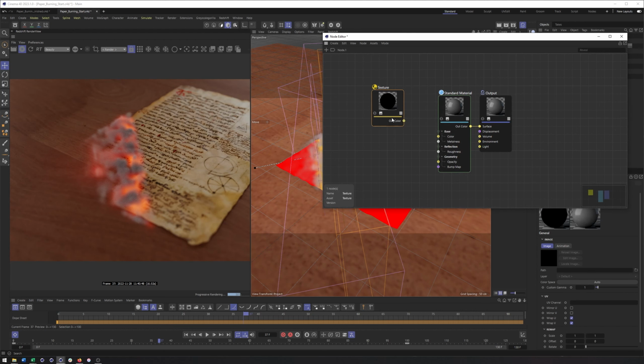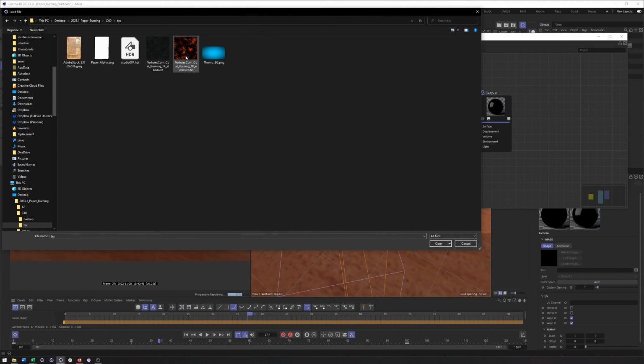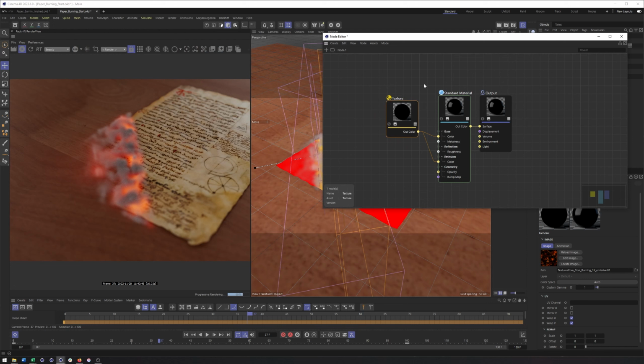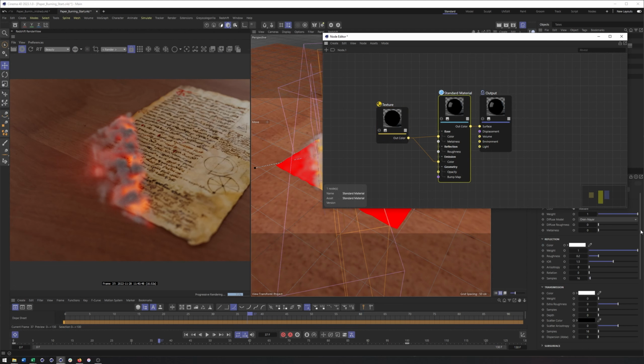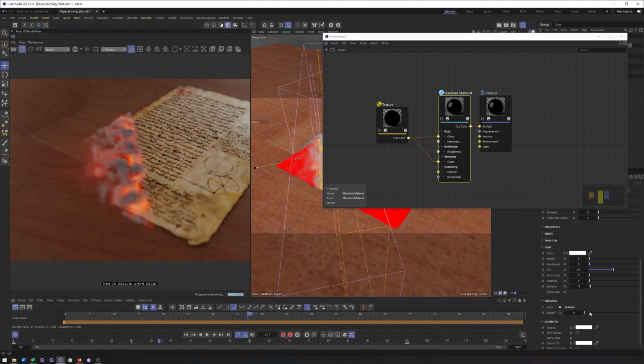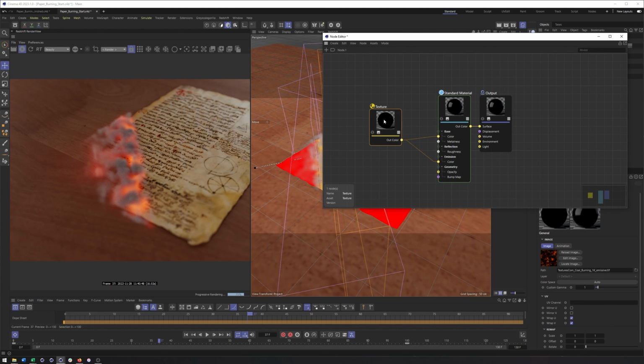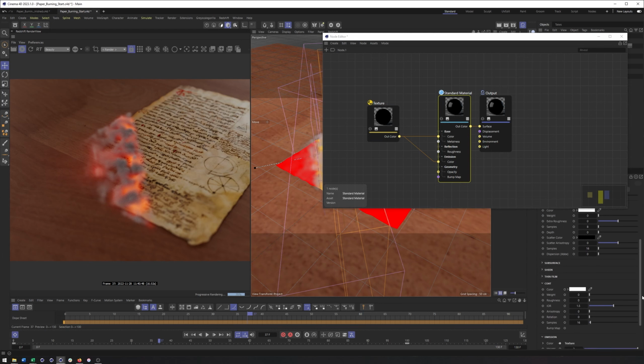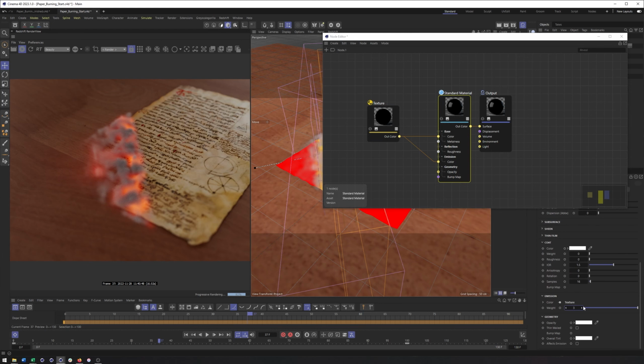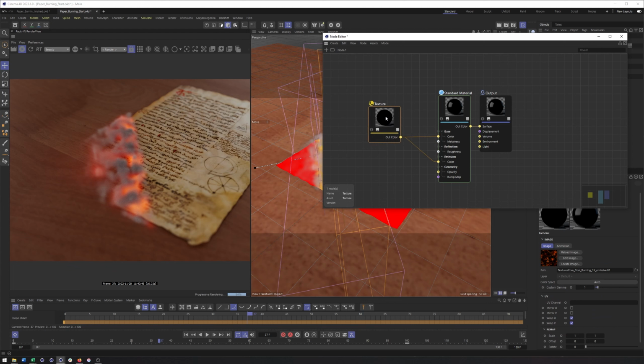and texture. And this texture I know is going to go into our base color as well as our emission. And this is going to be our kind of coal burning texture, which kind of works, kind of doesn't. I probably should have just used a noise and made it myself. So I did turn up the emission weight as well, just so we could see that. Could maybe even go higher, just based on my previous tests. And I'm also going to increase the scale here because I know it'll make it smaller.